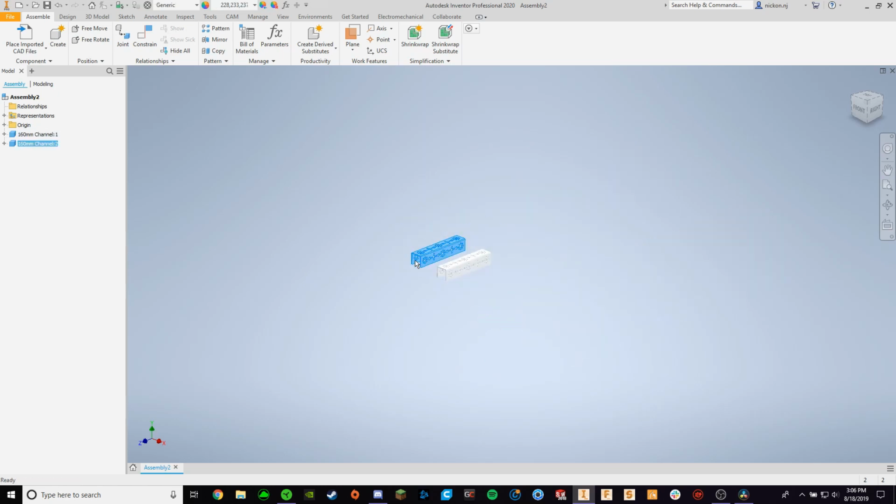So rather than going through the placement tool again, we can really quickly clone parts of an assembly by copy and pasting it. Again, just like Microsoft Word. And you'll find that quite a few keyboard shortcuts work in Inventor that are just generic to Windows. So select the part, press Control-C, and then Control-V. Now you have a copy of the part.